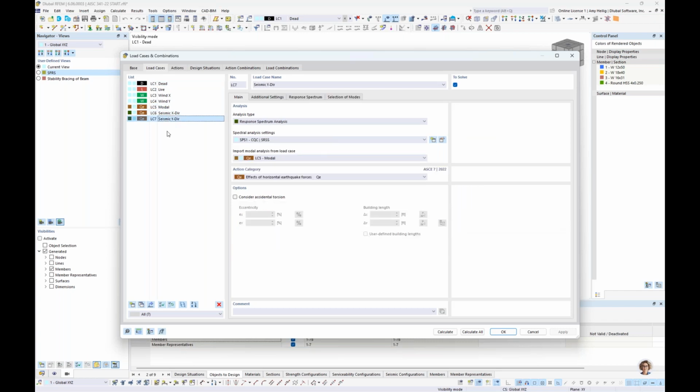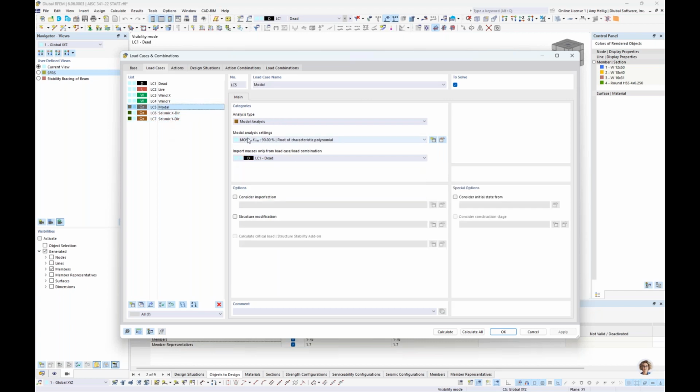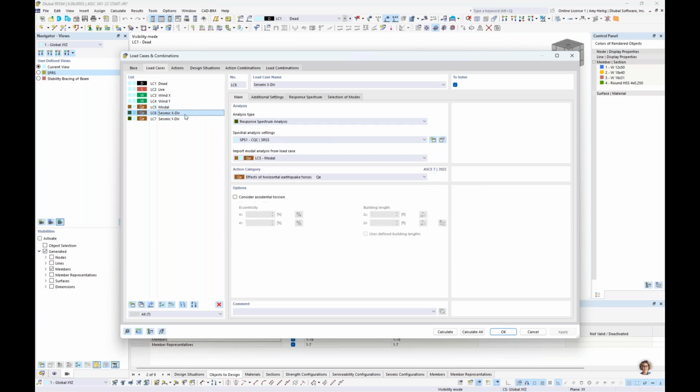Now, we definitely don't have enough time to go through this in detail, but we do have a previously recorded webinar on AISC 7 as well as the NBC for a response spectrum analysis that you'll find also on our website and YouTube channel. But you'll see here that we do have a load case for our modal analysis, and then a separate load case is defined for our response spectrum in the X direction, as well as a separate load case here for our response spectrum in the Y direction.